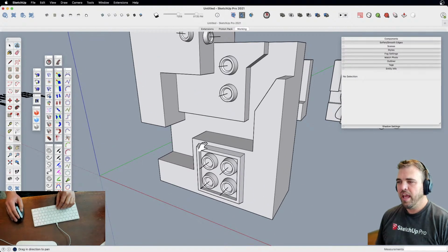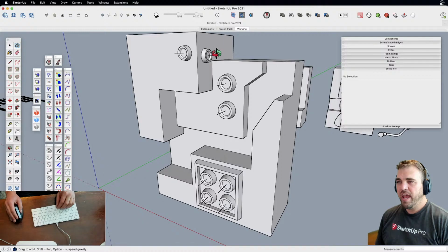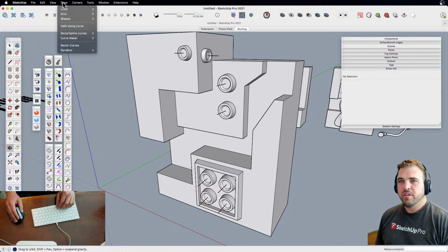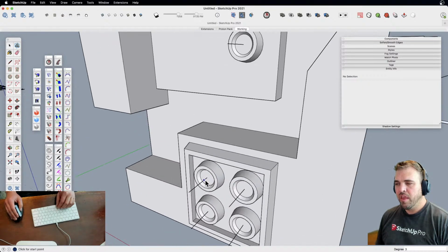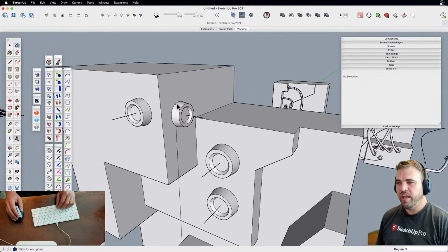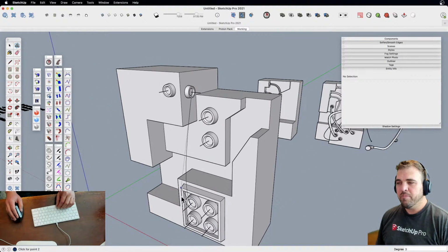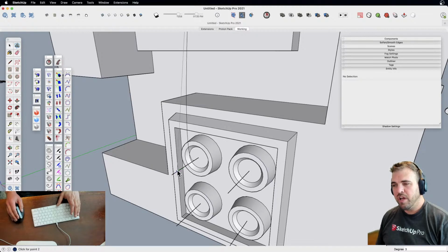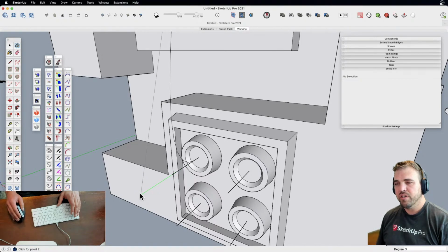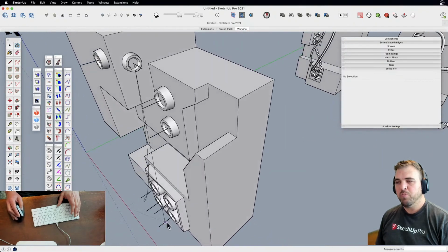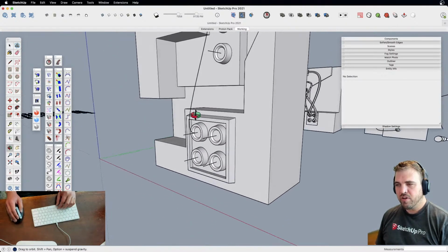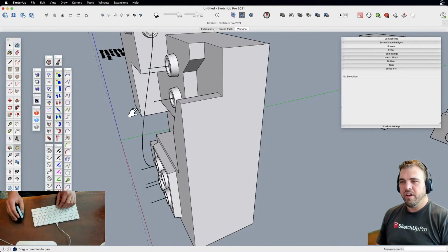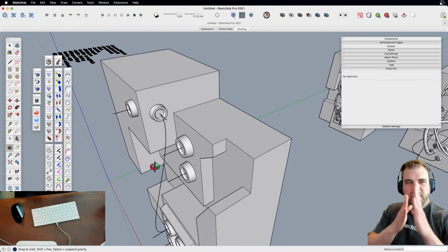So let's do that up here. Just to show, we can start here and then turn direction. We're going to draw a Bezier curve from here, 1, and it's going to end up here. Now I'm going to come back to this one where I want it to come in correctly, so I'm going to draw it somewhere along this edge. And I can keep going. If I pull out here on the green direction, so I click here, then I've got one more click. I'm going to draw up here and extend that out on the red. Now I've got this nice curve that exits from down here, curves up, and enters in a different direction.